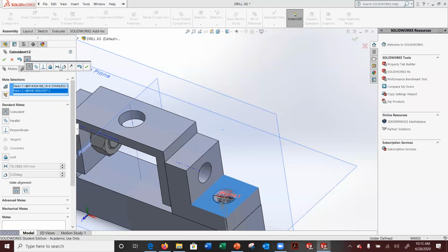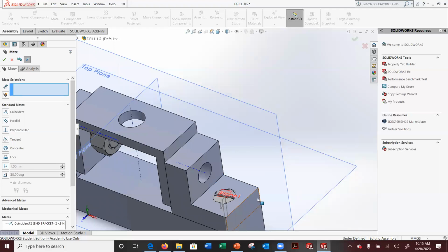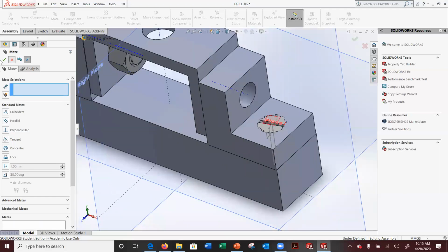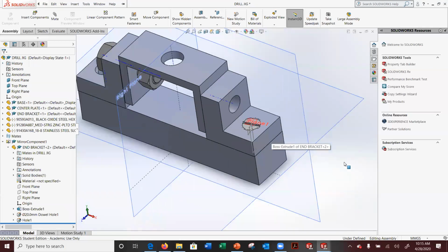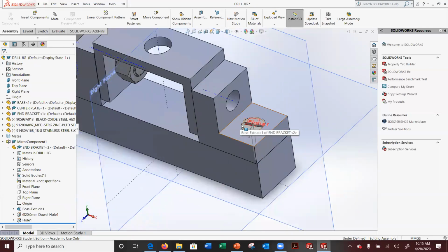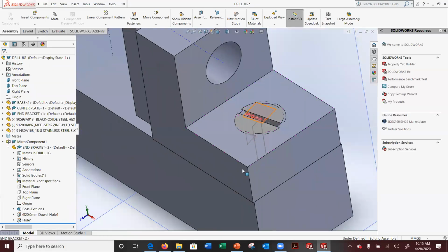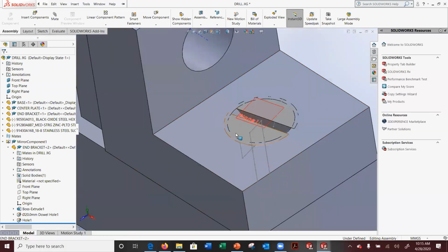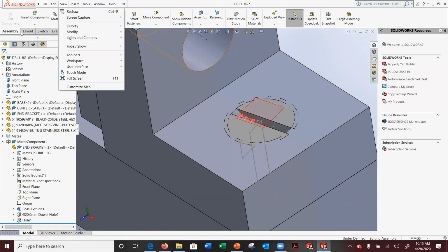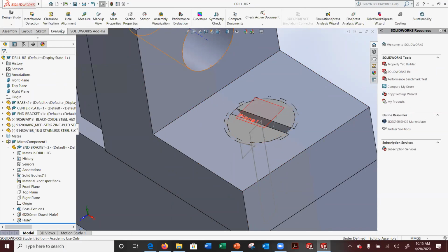Who noticed that there was a problem? Who's done the assembly yet? Yeah, one of the problems was the angle was 82 and the other one is 90. The angles are bad, as you could tell, and the diameters don't match, because as you could tell, there's a serious interference fit. Yeah, the diameter of the body, the screw is different than